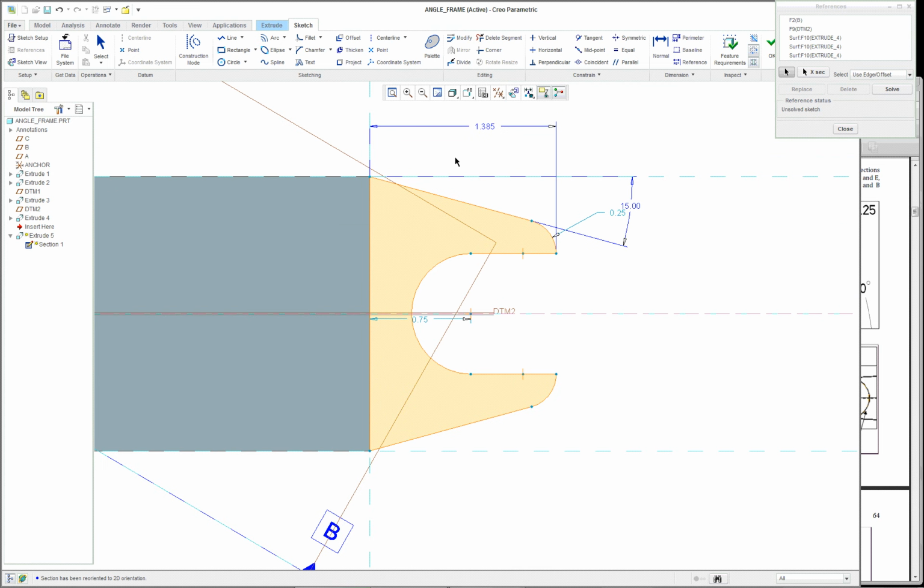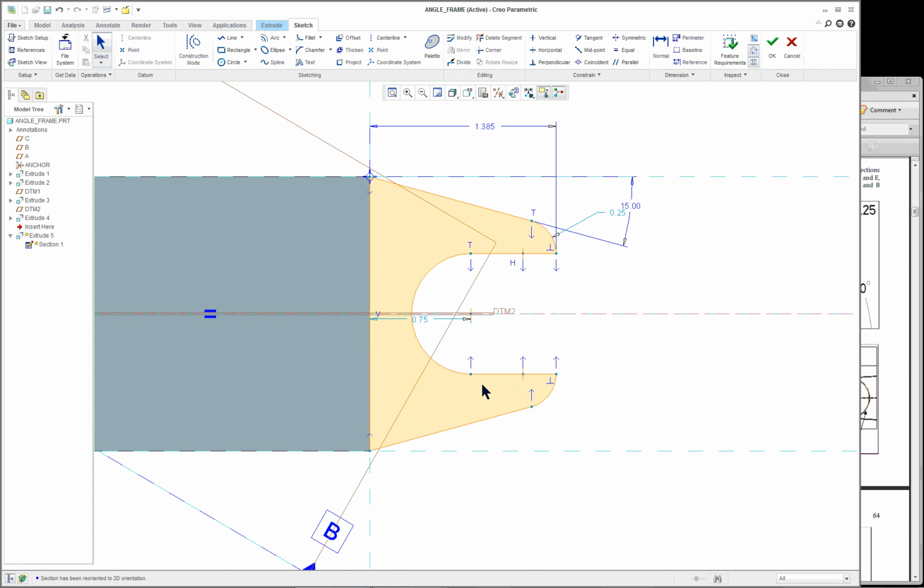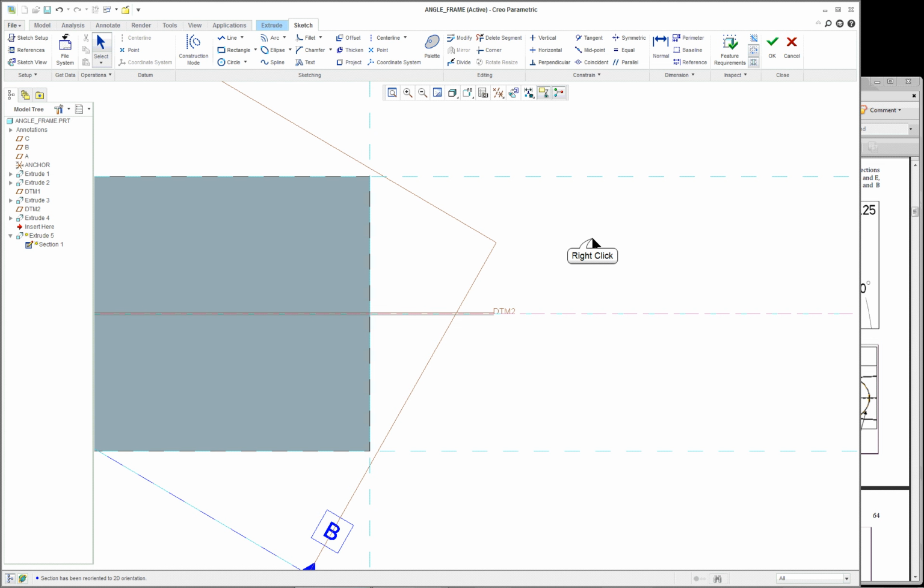I only have a few dimensions here. A lot of constraints. So, for instance, you would start off with a center line, and you can do a circle, you could do a line. There's a lot of ways to approach this one. So in this case, let's do line chain. Start here, and just go out there at an angle. Any angle is fine.